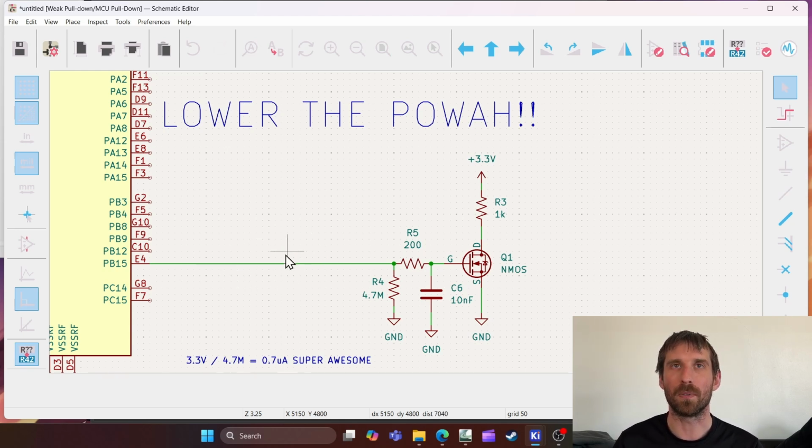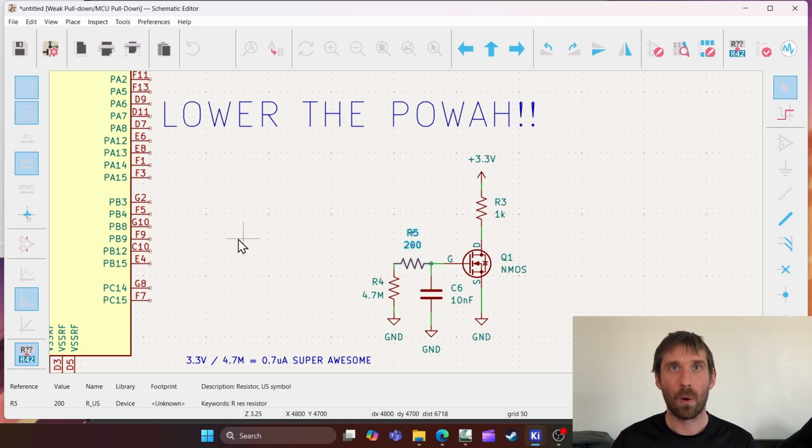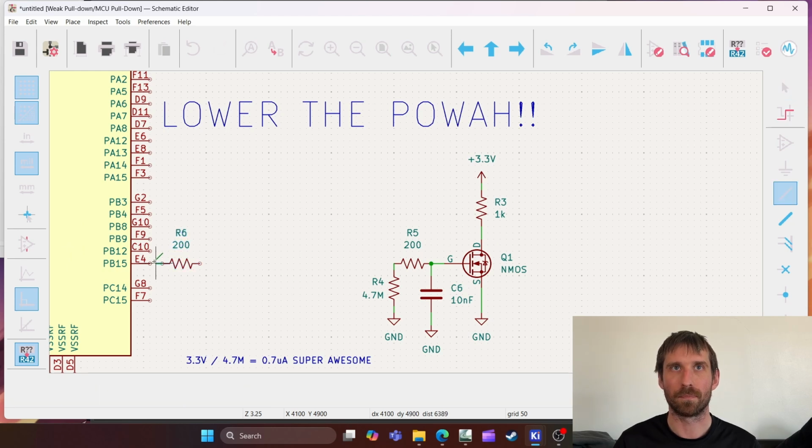Any noise that couples on here is going to go through that inductance, raise all that voltage, and it's just more for this to sink. Let's assume this is a long trace. This kind of works as a termination resistor also, but what can help is one that's physically close to here, as well as one that's physically close to here.